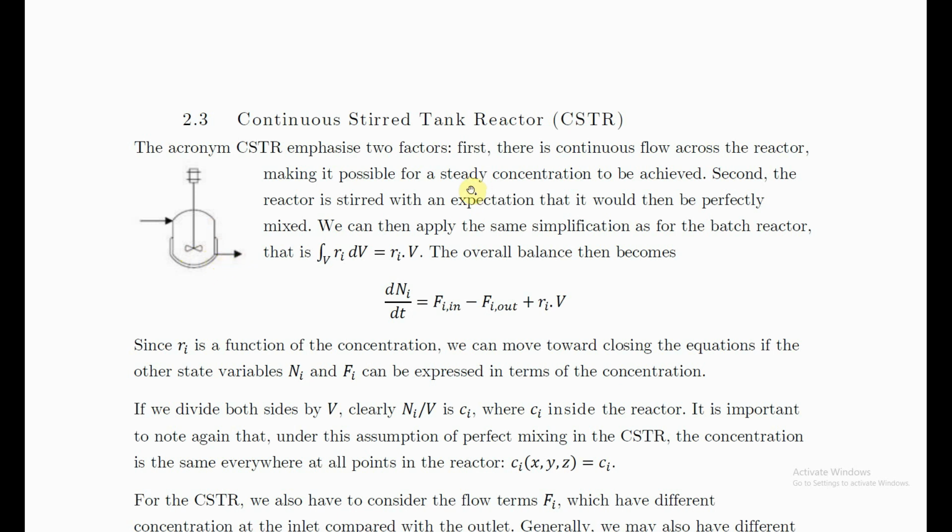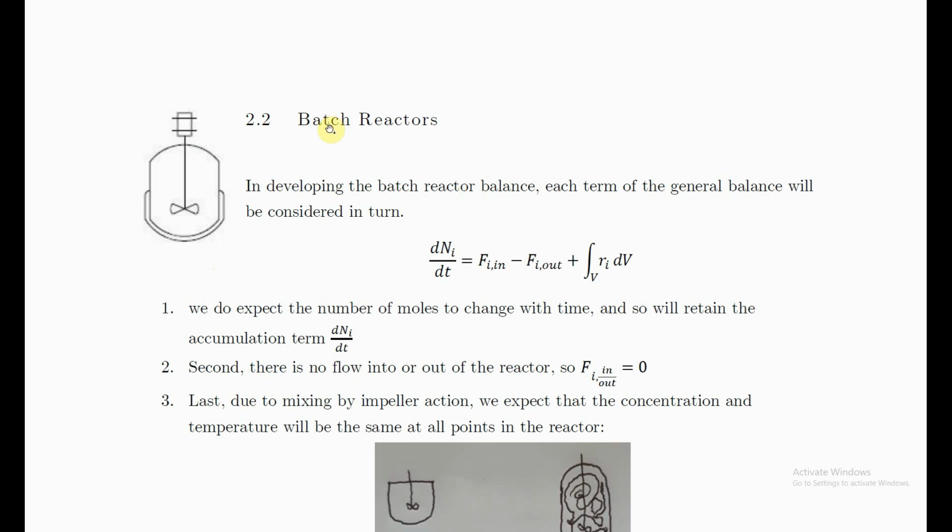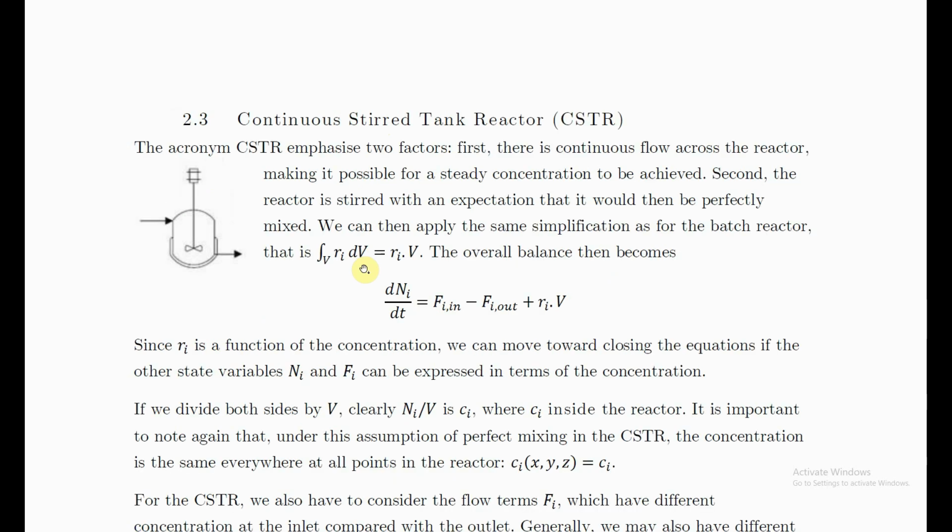And that's a bit different to the case of the batch reactor. So initially you charged with 100 moles per cubic meter, and then as time goes on, that does reduce, and as you get to the higher conversions, your reaction rate goes down. But at least initially, you had that 100 moles per cubic meter, so you had a high reaction rate initially. So with the batch reactor, you can at least find a region in time where you had a good reaction rate. Here, the higher your conversion, the more you are stuck to a low reaction rate.